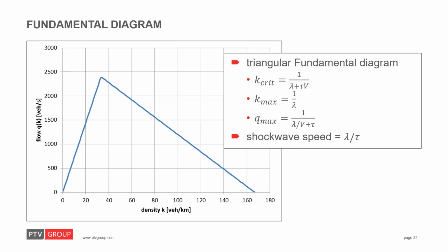To do so, you can use the fundamental diagram. The fundamental diagram shows the relationship between macroscopic quantities such as flow, speed, and density. Here in the example, density in vehicles per kilometer and lane is shown on the x-axis and flow in vehicles per hour on the y-axis. So it is very convenient that one can use the parameters of the curve following model to describe properties of the fundamental diagram. The formulas for the macroscopic quantities are shown on the slide.